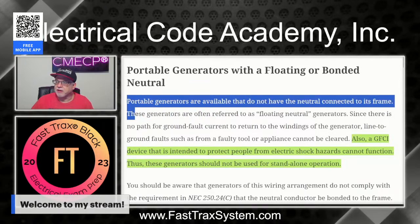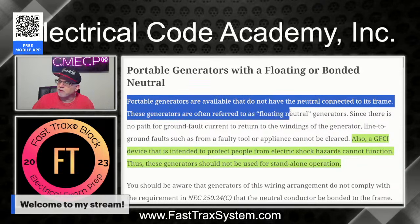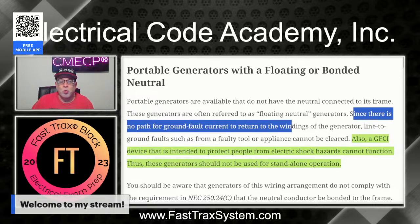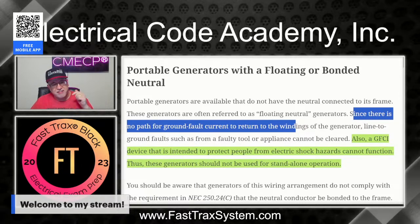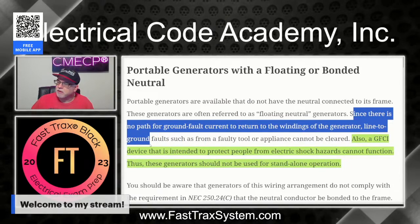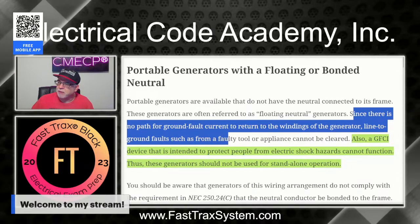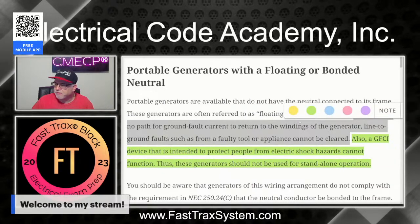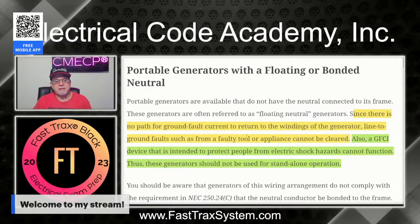These generators are often referred to as floating neutral generators. Since there is no path for ground fault current to return to the windings, to get back to the source, because it doesn't have that jumper, line to ground faults such as from a faulty tool or appliance will not be cleared. They will not operate the overcurrent protective device properly. So it creates an unsafe condition.